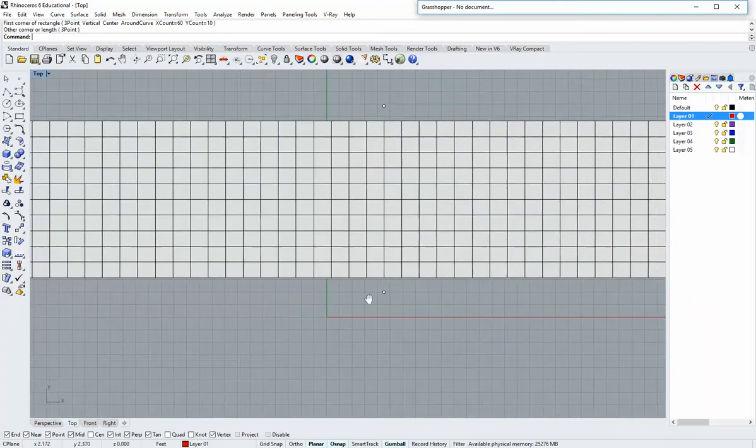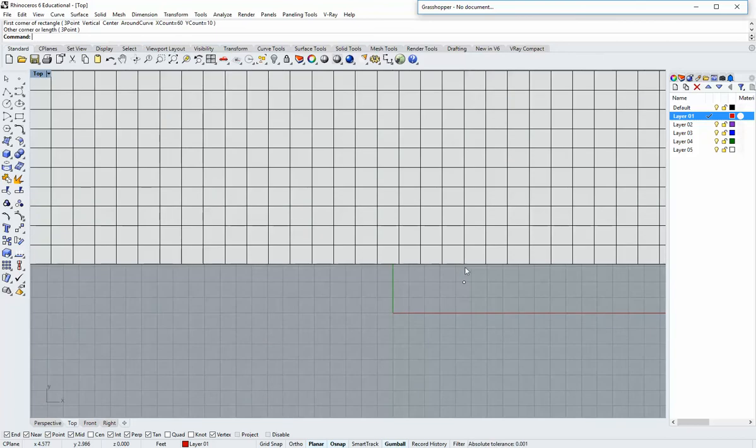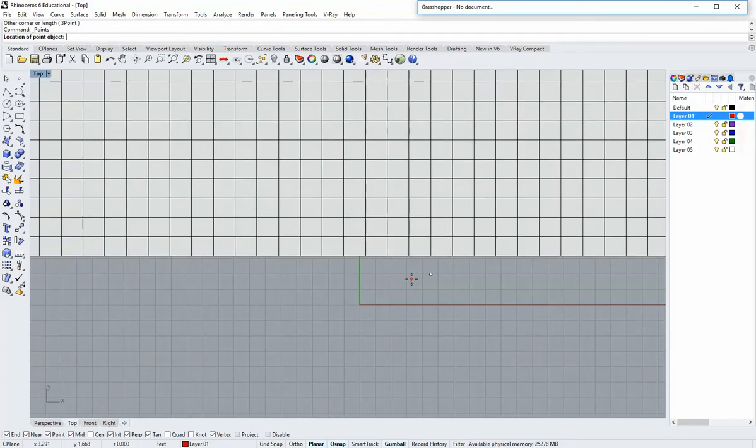Follow along. I've done a little test and gotten a decent proportion out of this. We're just going to count off from this point here. We're going to count off a few lines, place a point, and keep doing that. In my red layer, I'm going to grab a point and count out 1, 2, and 3. On the third line, I'm going to draw a point, which puts 3 mesh faces between the center point and where I want that point. Then I'm going to go 3 again, 1, 2, 3, and then exit that command.